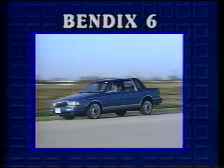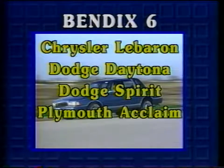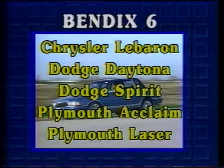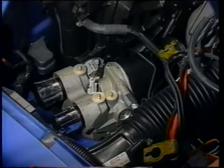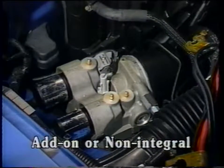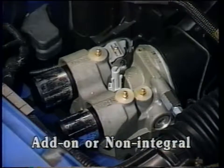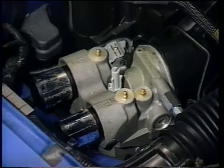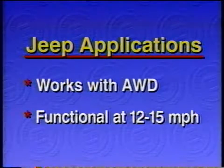The third ABS system we're going to look at is Bendix 6. It's found on 1991 and up Chrysler LeBaron, Dodge Daytona, Dodge Spirit, Plymouth Acclaim, and Plymouth Laser models. Unlike the other 2 Bendix ABS systems, Bendix 6 is an add-on or non-integral ABS system. It has a conventional master brake cylinder and power booster with a separate hydraulic control modulator for anti-lock braking. Let's start by taking a closer look at the Bendix system that's used on the Jeep applications.